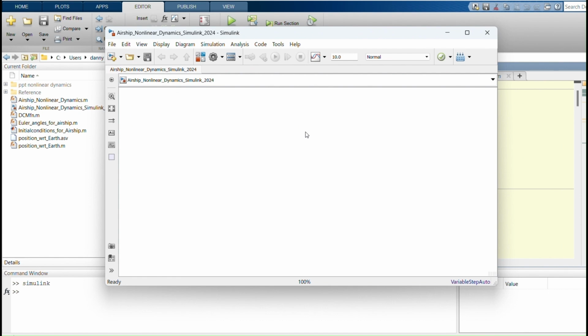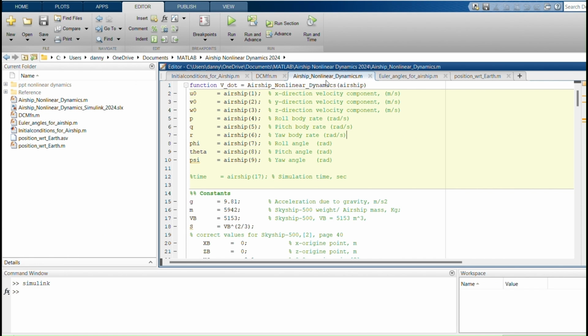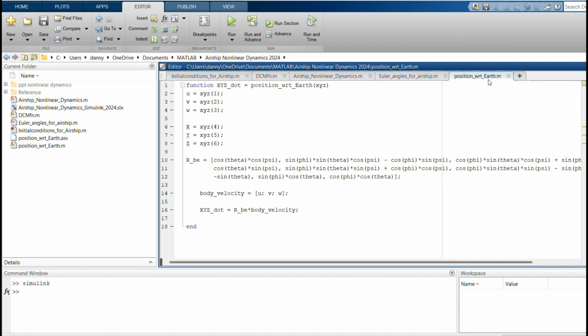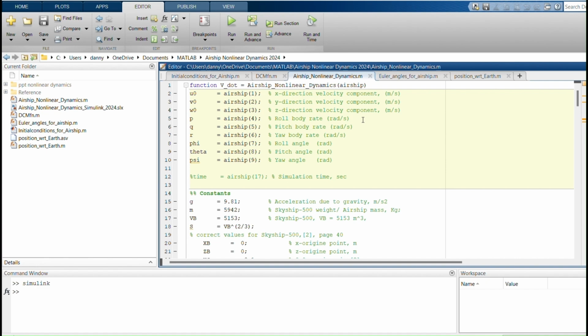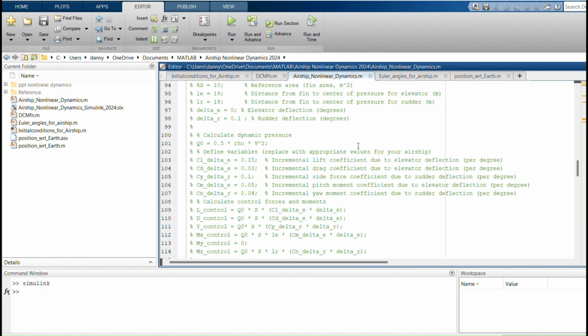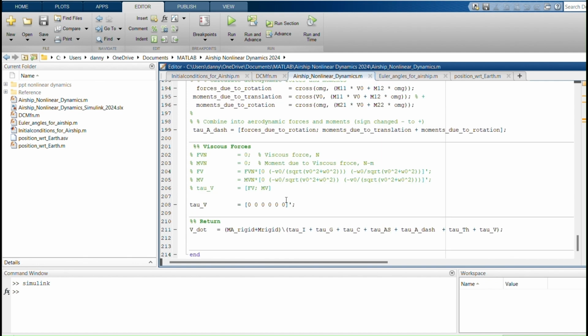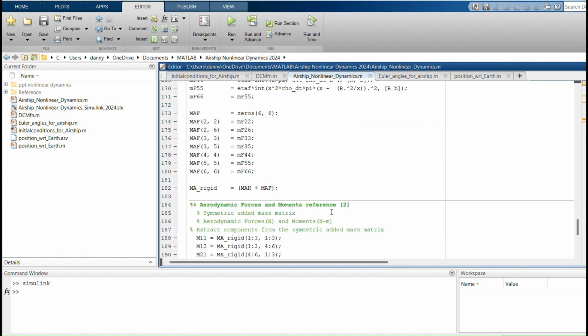Now what we need actually is to access these functions in the environment, and integrate these dots to estimate the state variables. We have the dot as an output here as well. All these three functions have the dot as an output, not the required state variables. So we need to integrate them. Simulink is going to be very helpful for that. We don't need to write anything. We just need to use a simple integrator block, which will be helpful to integrate everything.